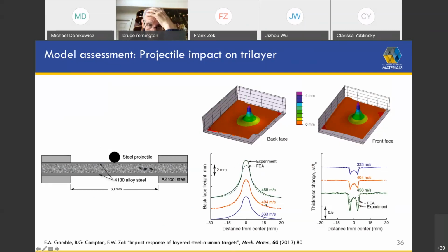And again, here we can compare the measurements with simulations. These will have to be done through finite elements, but we now have a constitutive law that we believe is calibrated and which can indeed be used in combination with the constitutive laws for the metals themselves to predict the response of these sheets in a much more complex type of system under dynamic loading.